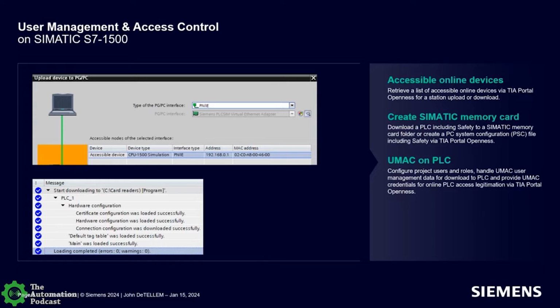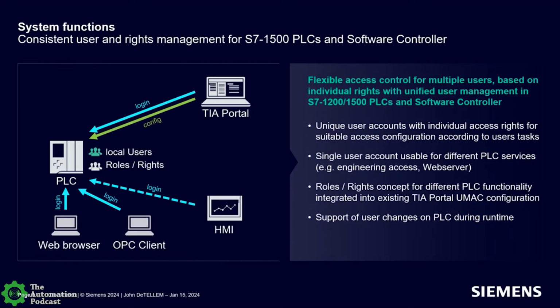That functionality was known as user management access control for the engineering inside TIA Portal, where I tied it to UMC or our Windows domain for the users. Now, if we set it up properly, the PLC is also capable of checking who's logging in and that they have the valid rights and roles for the features and functions of that PLC. So this is the first step in bringing the PLC into that user management.